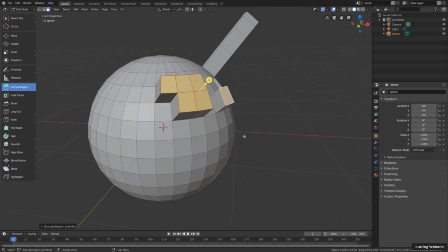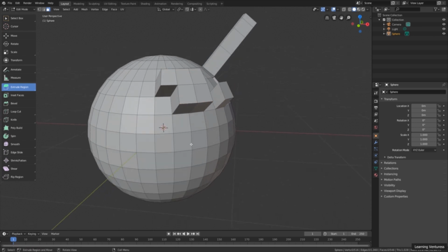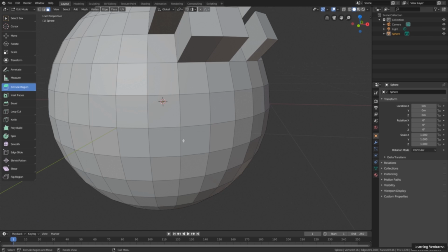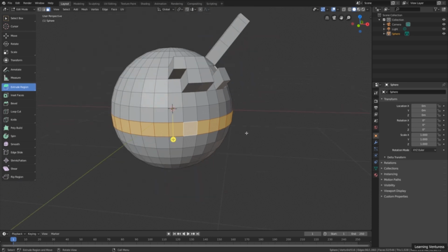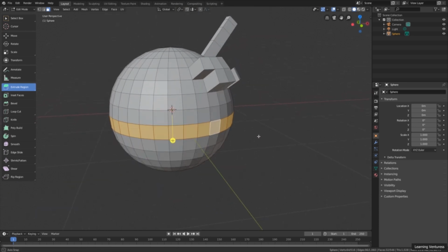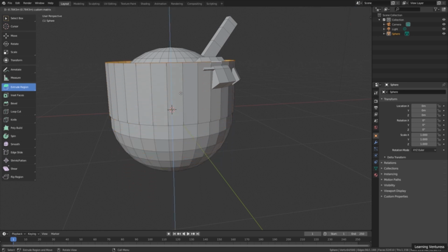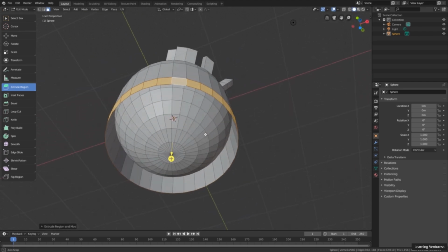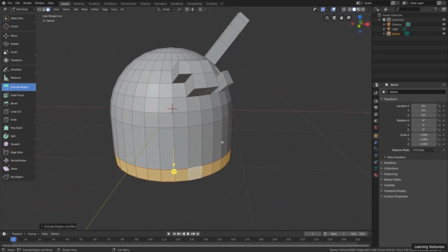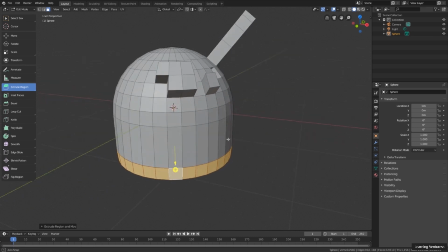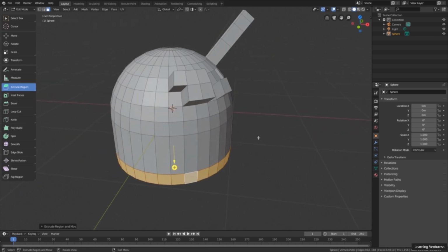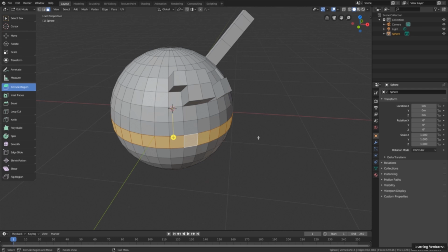Then I will select an entire loop here from the sphere by holding down the Alt key and clicking next to one of the vertical edges of one of these polygons. And now I will click on the edge icon of the extrude and drag. As we can see, the result is a bit strange, because all of the polygons are extruded in the same direction. Then I will undo the command using the Ctrl-Z shortcut.